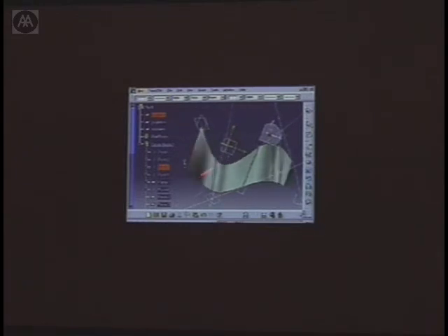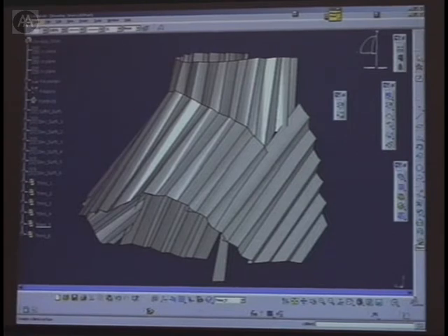At this point, I know that I don't have to worry about that Gaussian curvature analysis anymore, because this is always going to give me single curved sheet metal unfoldable material that I can basically run off a coil, and it comes with a certain cost per square foot or per square meter, and that allows me to define the cost of my building. You can take something and design with it, so something pleated or something like that. It doesn't really matter what the shape is. The point is that this can be made in a certain way.